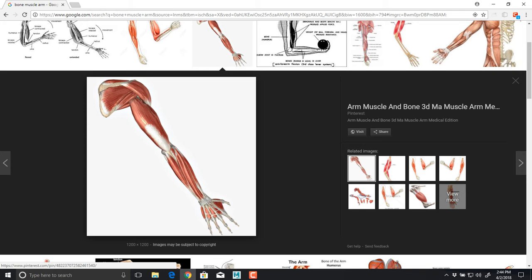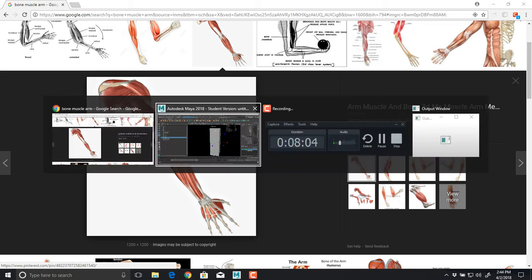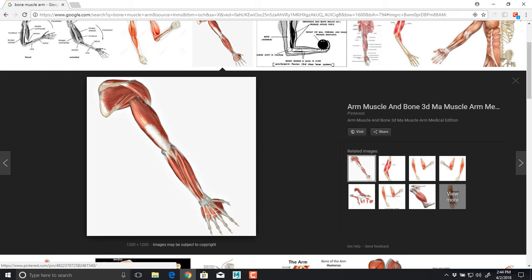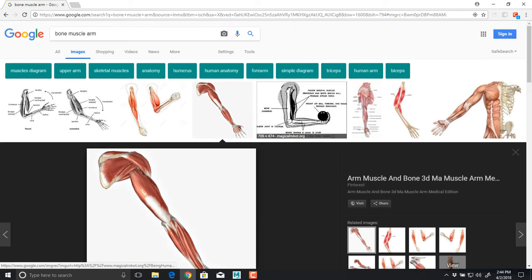Also on the fingers, each one of your finger joints, even though you could probably twist your fingers a little bit, you typically on a robot wouldn't do that, right? So most of your finger joints are going to rotate just like this, just like hinge joints right here and hinge joints right there, with the exception of this base one that would be a hinge joint this way and kind of a side to side as well, okay? I would actually just do hinges for each one of those areas and then worry about the stretching somewhere else, okay? So definitely look at this kind of stuff so you can actually understand it if you don't understand it.